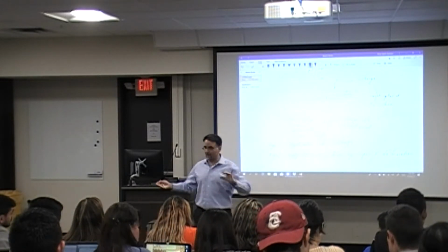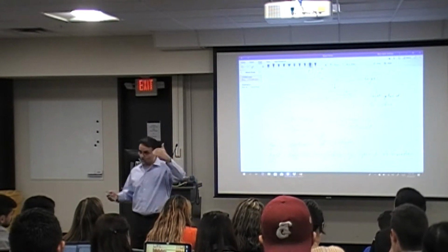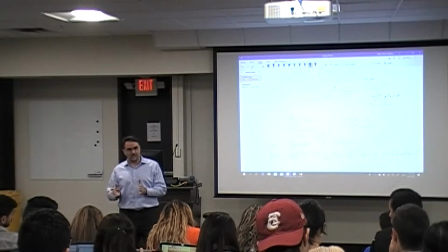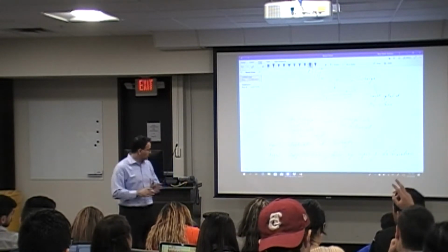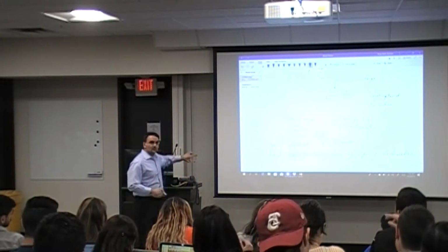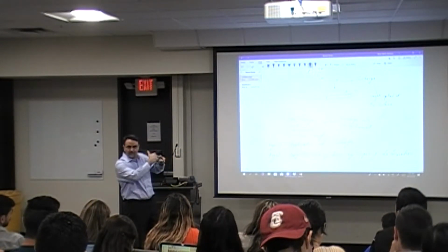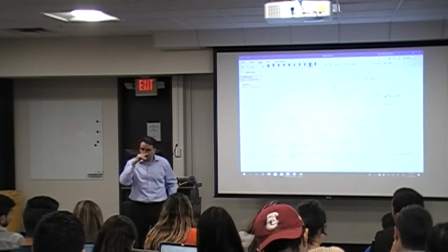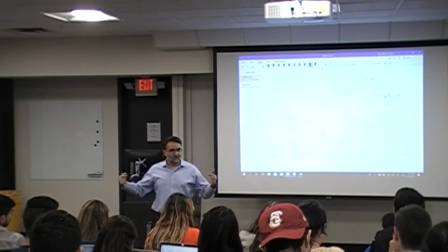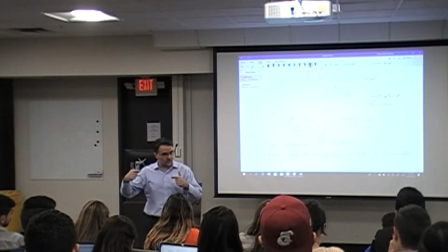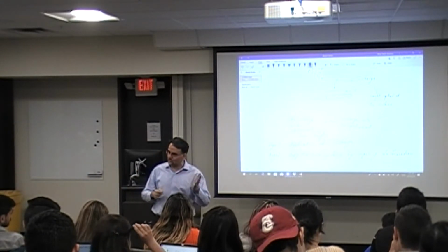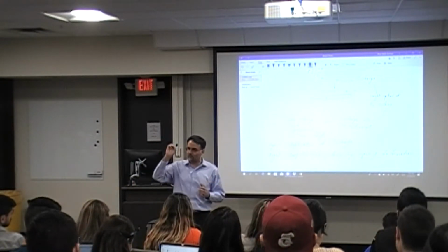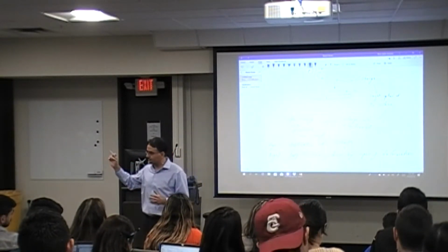Load divided by area. You have the weight, right? The surcharge is going to be normal, right? It's going to be perpendicularly downward. And the area that resists that from the top is going to be that segment here, right? So this is going to be the area that resists that normal load. Now, how do I calculate the shear stresses? This would be the shearing resistance in the horizontal divided by the area that resists that, right? So those two components are required to be able to find those points along the failure envelope.